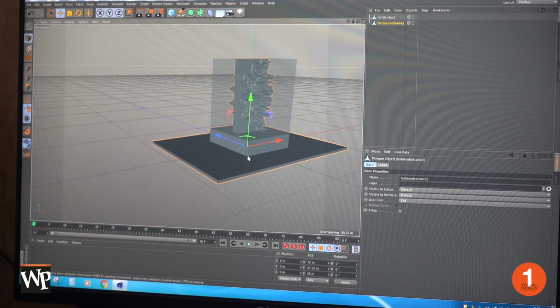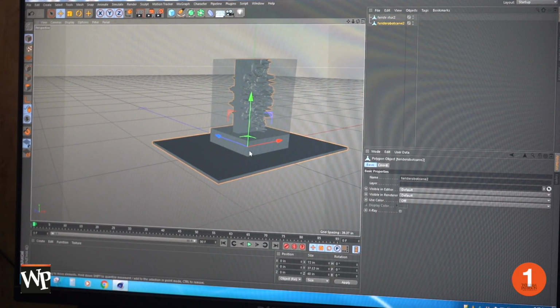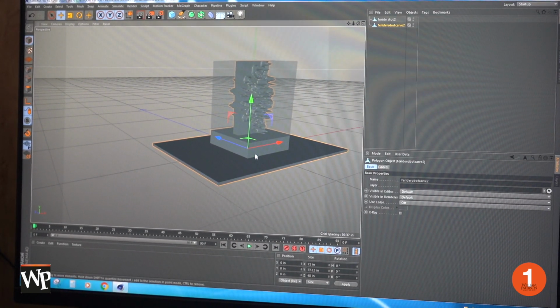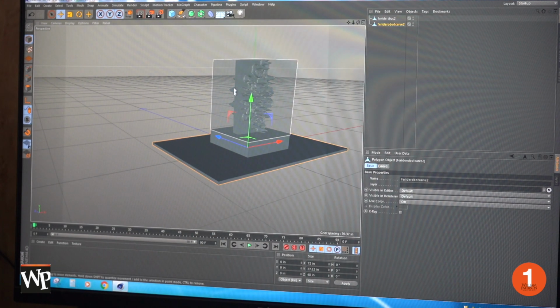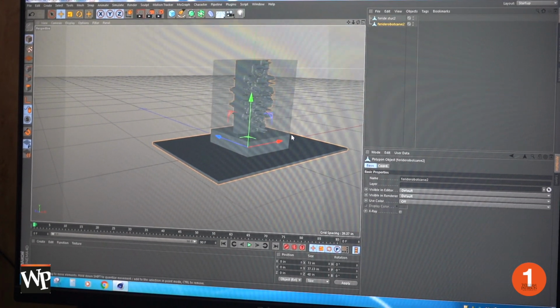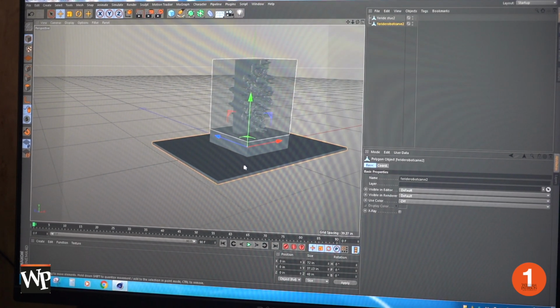So we make this 6 inches, because then that lets us avoid our L brackets that we put in to hold the piece, and we don't have any issues with accidental collisions with the bed.